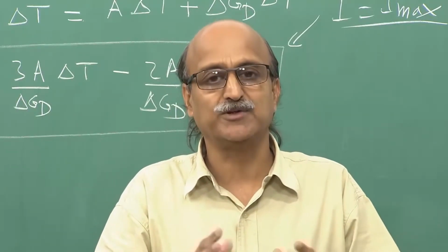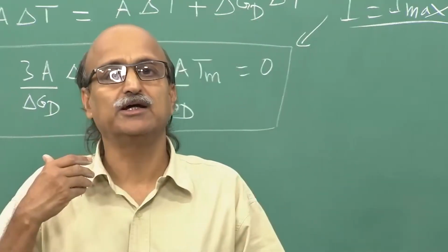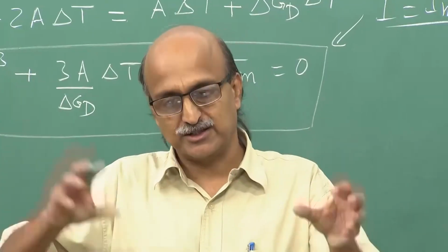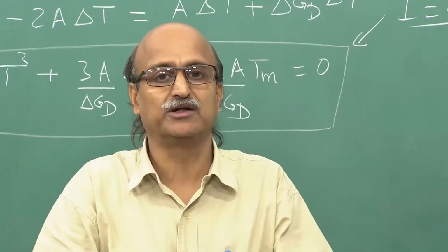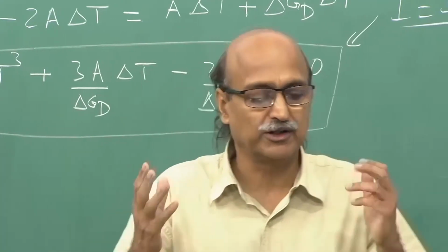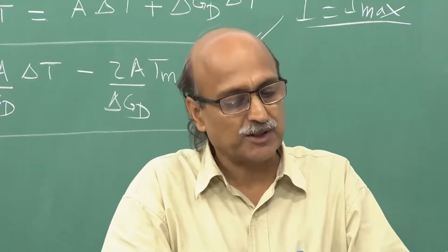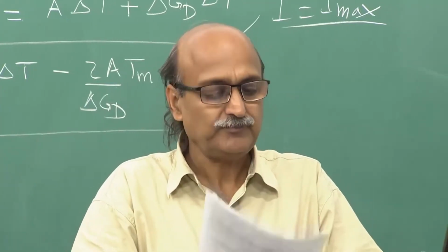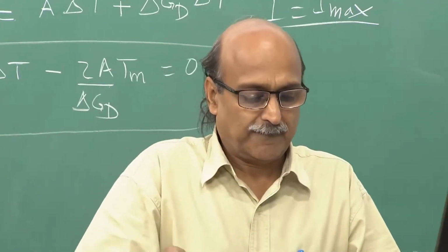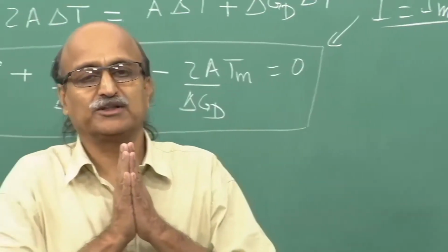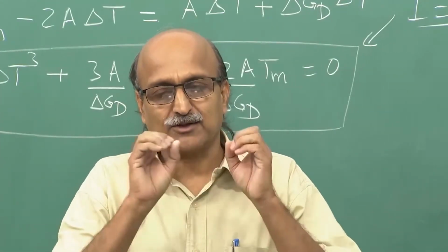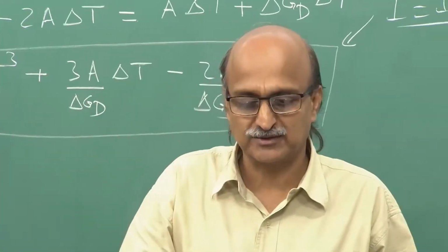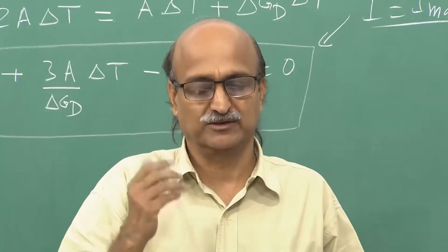Once the nuclei form, they have to grow, so we will be looking at how fast they will grow. By taking the nucleation rate and the growth rate and putting them together, we would get the overall transformation kinetics. But before we go into the growth kinetics, what we saw here was that the undercooling required for homogeneous nucleation of ice to take place was of the order of 42 degrees.